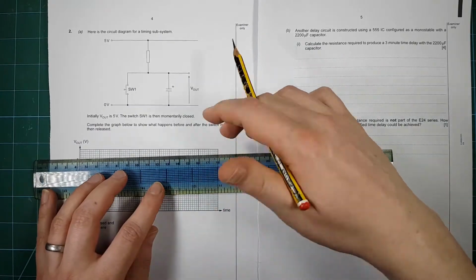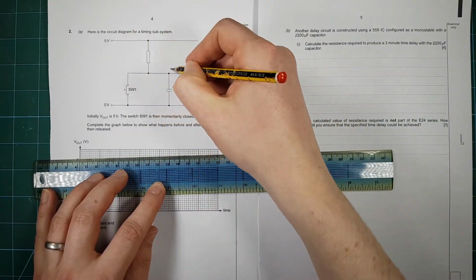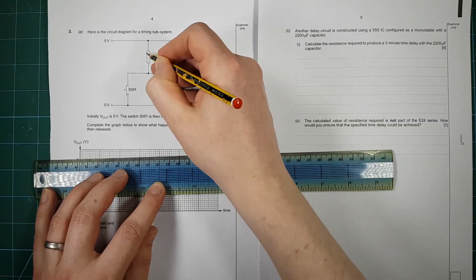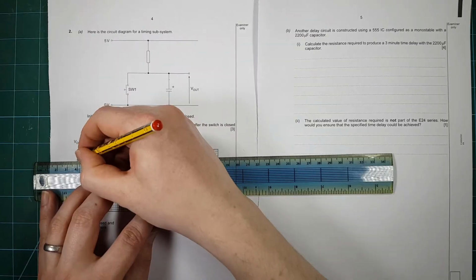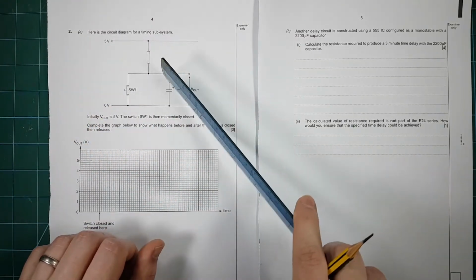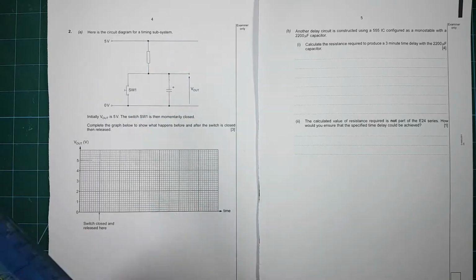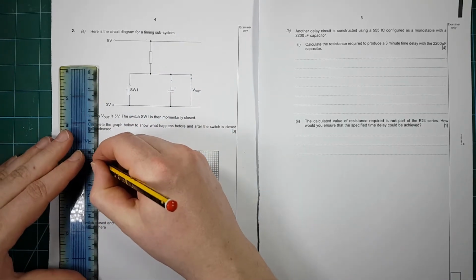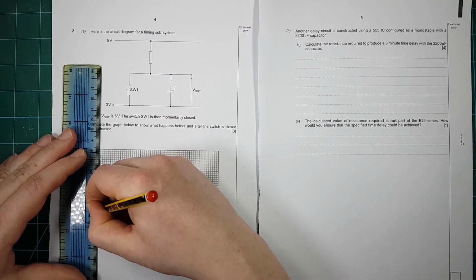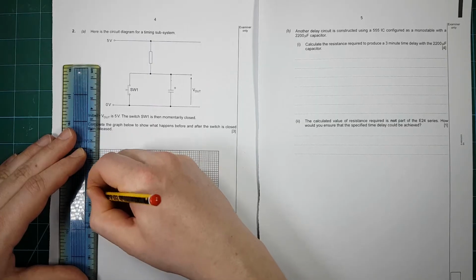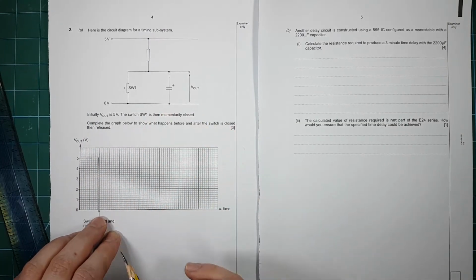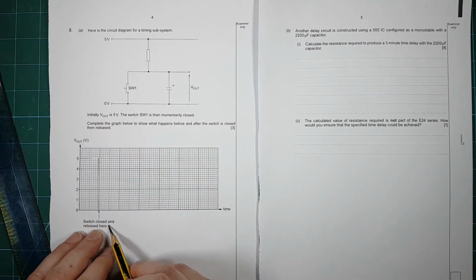So when we push the switch, it starts off after a long time fully charged up to whatever this side of the capacitor is connected to, and it's connected through this resistor to 5. So it starts off at 5 volts like so. When you push the switch, this is a very, very quick discharge because the resistance of the switch is tiny. So it will discharge really quickly. RC is really low. Discharge really quickly down to ground there,